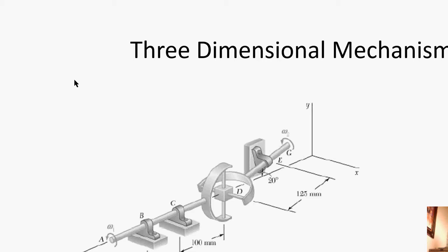If you don't do that, we had this issue that when you bring it in, 1 inch is 1 meter, and that's not correct. So there's a way to do it. I'll repeat: save it with the units as meters and read it with the units as meters. Whether you work in inches in the drawing or later convert to inches on the SimWise side, it doesn't matter.